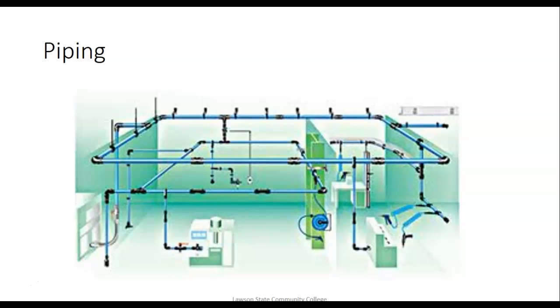So that's the problem we have with gases, is that we can't run them at extremely high pressures because if you do, they will turn into liquids. But we don't have to vent it, I mean, we don't have to bring it back to the tank. If it's air, we can vent it. And at lower pressures, your piping and everything doesn't have to be metal anymore, we can make it plastic. But your cylinders have to be bigger to do the same amount of work, and you can't control it as well.